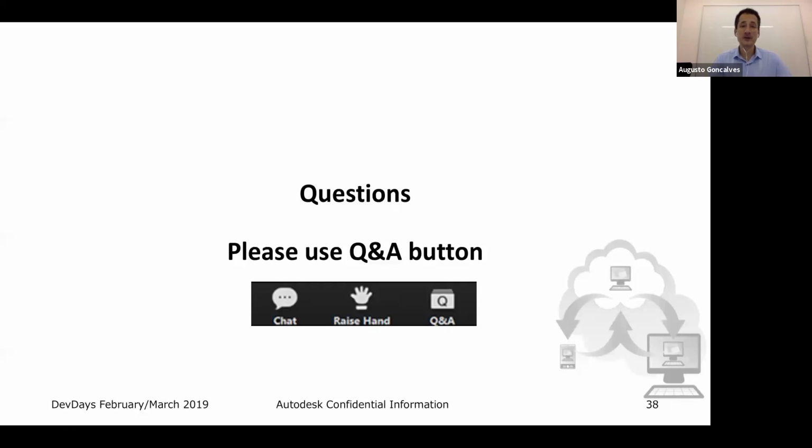And the reason this is important is that design automation runs on a service that is costing us, right? We don't want to hold the application until your user will input the data. So it's better to get the data before the process and get the output. Essentially, design automation is a batch processing tool, so when we're talking about batch processing, we don't get input during the processing. So yes, you can get data, but get it before you start the processing of the file.